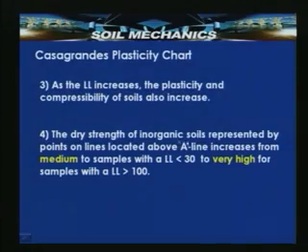The dry strength of inorganic soils represented by points on lines located above A line increases from medium for samples with a liquid limit less than 30 to very high for samples with a liquid limit greater than 100.